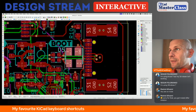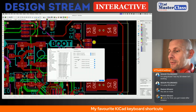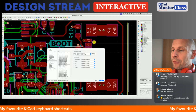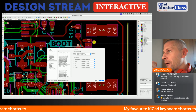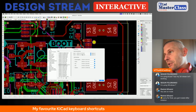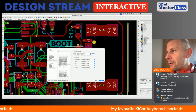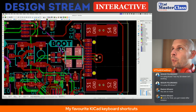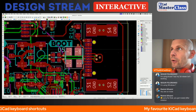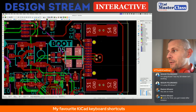I said that I very frequently use, like 100,000 times a day, fast changing of the grid. Grid 1, I use a 1 mil grid for component placement and routing, and option 2 for grid 2, 0.5 millimeter, for edge cuts like the PCB shape, position of the connectors, and similar things, mounting holes. So pressing option 1, I don't know what the shortcut is on Windows or Linux, is the routing grid, and option 2, 0.5 millimeter, for bigger things.